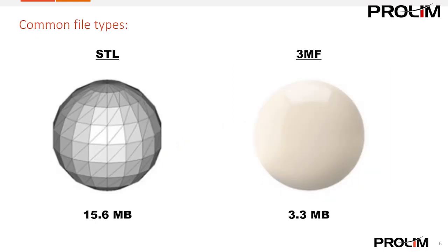Now we're going to look at common 3D file types within Solid Edge. The original STL format, or stereolithography, or even standard triangle language, is the original file type that was first created to translate CAD data into third-party 3D printing software. It works by creating a series of small triangles to produce edges and curves of a model. This file type only maintains the surface geometry of a model without any representation of the color, texture, or model attributes. It is specified in both ASCII and binary files. Binary are more common as they are more compact. This file type is ideal for quick, low-quality 3D prints.